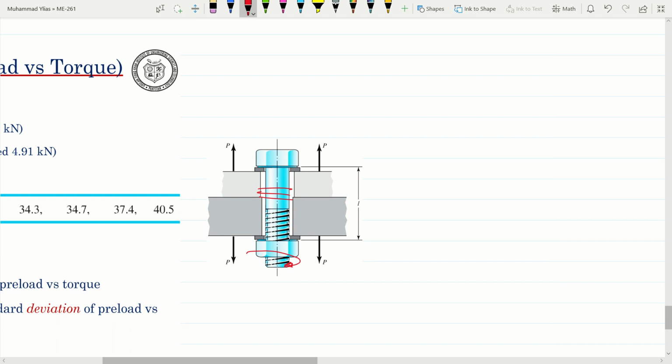One more consideration while making these bolted joints, usually we prefer to keep either the bolt or the nut stationary and twist the other component. Once again, this avoids the excessive shear being generated in the shank of the bolt.